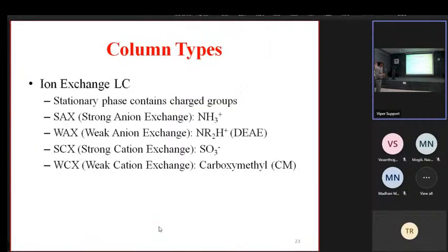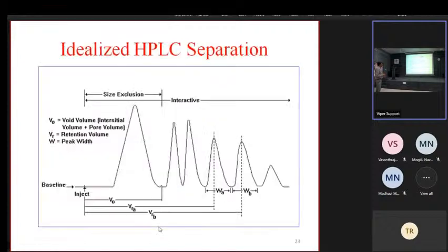These are the columns, the spectra I'm looking at. You get the spectra like this. Maybe C is eluting after 5 minutes, so its retention time is 5. B is eluting after 10 minutes, so its retention time is 10. And the area under the curve is the concentration. If the sample contains a larger quantity of A, you will get a higher peak. The area under the curve is the quantity, and